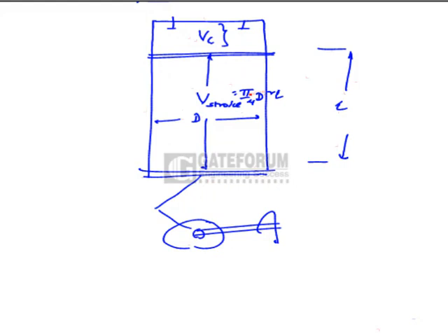The actual volume of air or air fuel mixture sucked into the cylinder during the suction stroke will definitely be lesser than pi by 4 d square L.